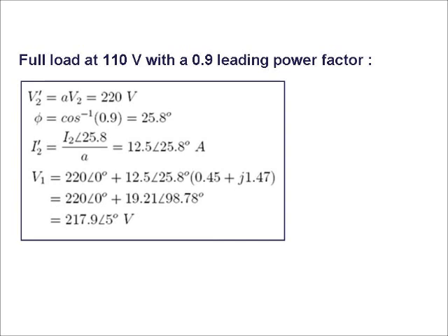So you have to know how to calculate phasors using complex numbers. When you have multiplication of complex numbers, you multiply the magnitudes and you add the phases. When you have a division, you divide the magnitudes, and the phase shift is the phase of the numerator minus the phase of the denominator. If the denominator or the numerator has a minus, you just consider that in your total phase. When you want to sum complex numbers, it's easier to use Cartesian form. So Cartesian form for sum or subtraction, and polar form for multiplication or division.